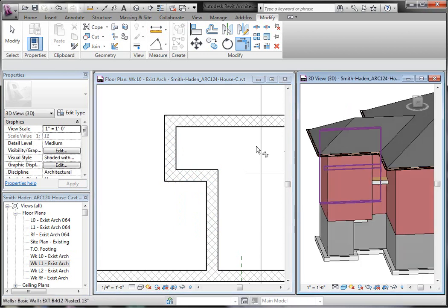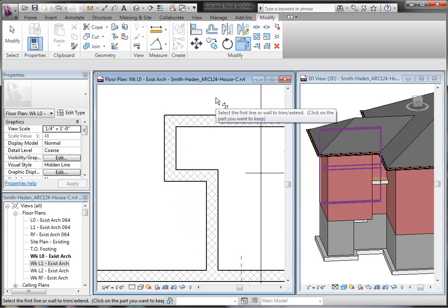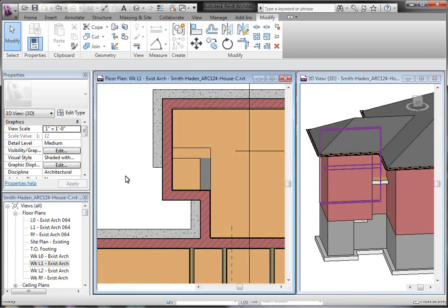And again, to get these two views side by side, I pulled them up one after the other. Escape out of the trim command. Pulled up one after the other, and then I did WT, and I've actually stretched them a little bit. And then I can control tab because I also have the first floor plan underneath there.